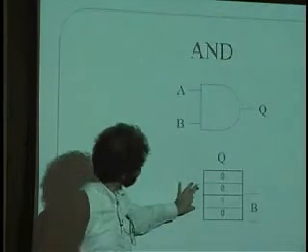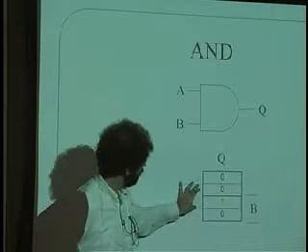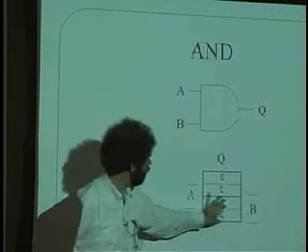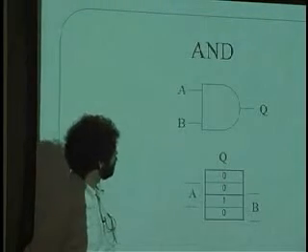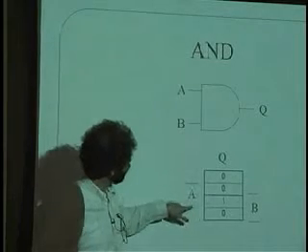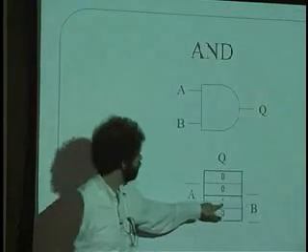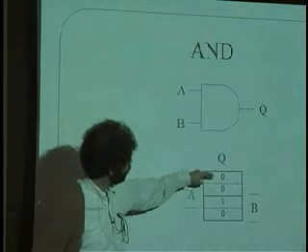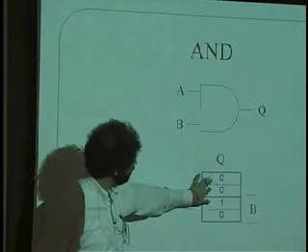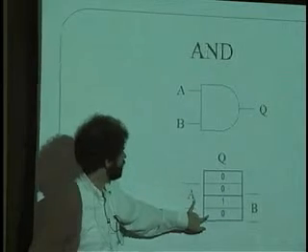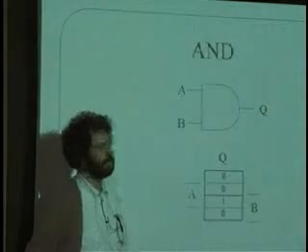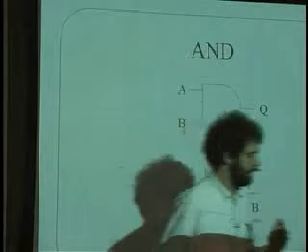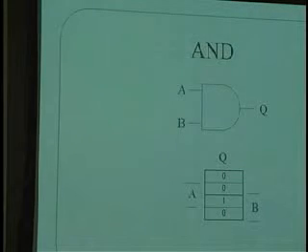So here's where A is true, here in the middle. And here's where B is true, over here at the bottom end. And you see that an AND is nothing more than, if A is true and B is true, then the output is 1. So again, it's a gray code. Both are low, one's high, the other one's high, and then the first one is low, and then going back to both of them being low. So that's the description of an AND gate in K-map form.